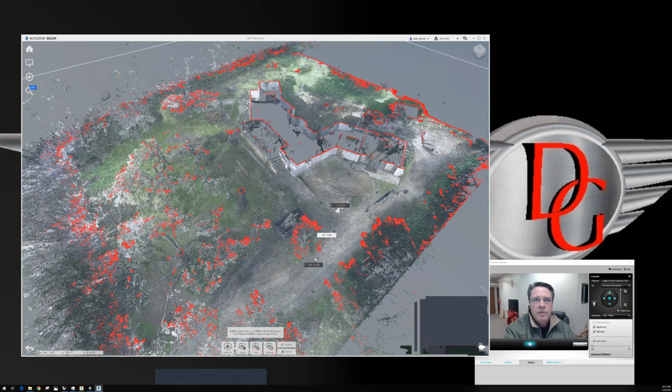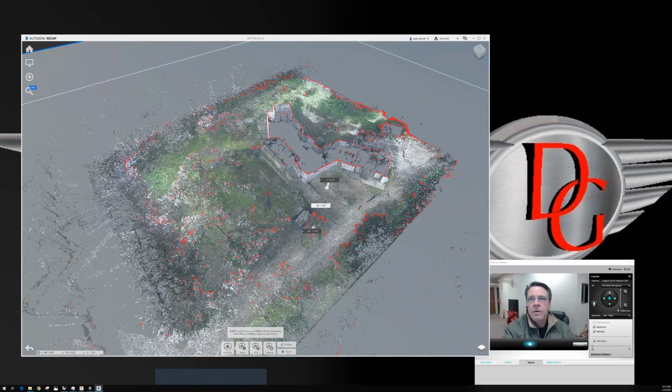A lot of times people want to have interior walls, check the thickness of walls, check a structure for square, what the footprint actually is. We'll scan the interior of the house and the exterior, and then we can do a slice like this and actually check thickness of walls, and we can also do vertical slices through the structure. So real quick, I'll show you that.